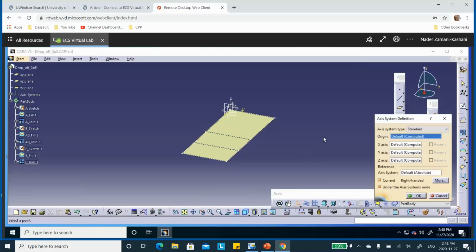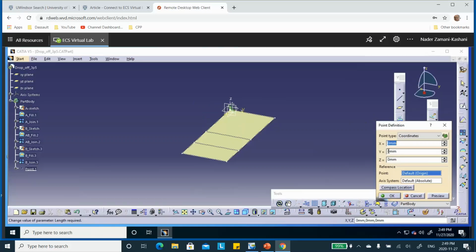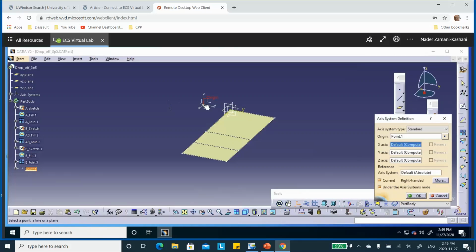Those were done in videos 2 through, I don't know, 4 or 5, so you can check it if you want. So the only thing is that I'm going to move the location of the default that's created here a little bit to the left. So put the cursor on origin, right click, create a point, and for Y, put down, how about minus maybe 30, 30, okay, fine. So it's going to be placed right there.